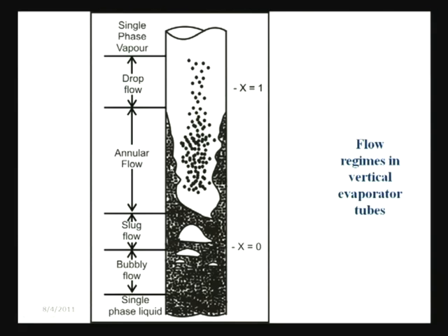Now, after the annular flow pattern sets in, we find that now the vaporization starts to occur not more at the walls, but predominantly from the vapor liquid interface, and gradually the liquid film starts getting depleted. Remember one thing, in this particular case, the liquid film gets depleted by two mechanisms. What are the two mechanisms? Firstly, some amount of the liquid gets vaporized into the vapor phase, and secondly, there is a liquid vapor shear.